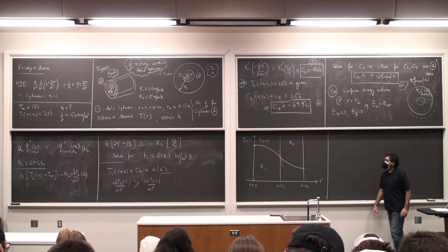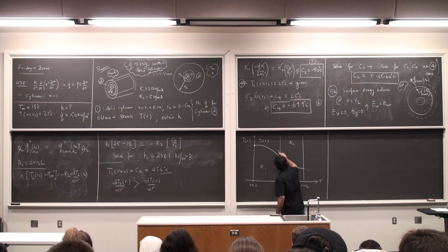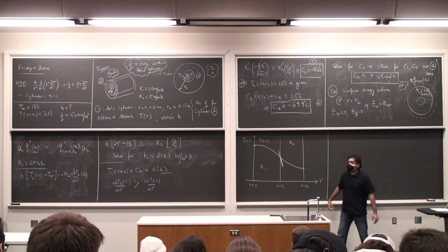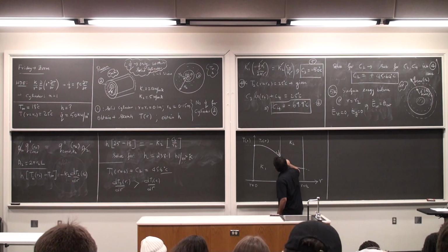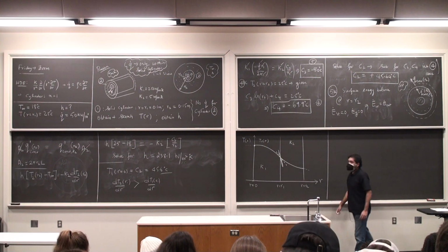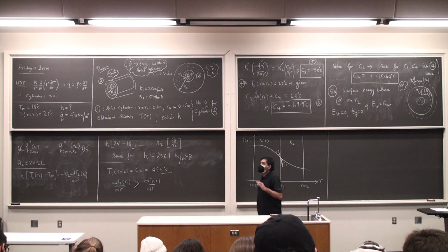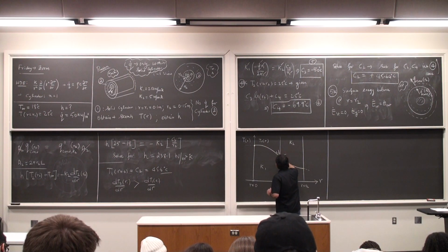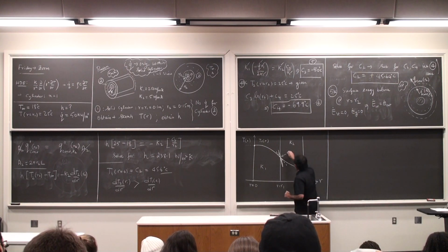So I go in this particular manner. There is a slope discontinuity here. This is the slope as I enter the material K2, and this was the slope as I exited the material K1. The temperature is still continuous. I cannot have two different temperature values at the same point. Okay, this is not an unsteady problem, and even in such a situation that is kind of impossible. So this is slope discontinuity.